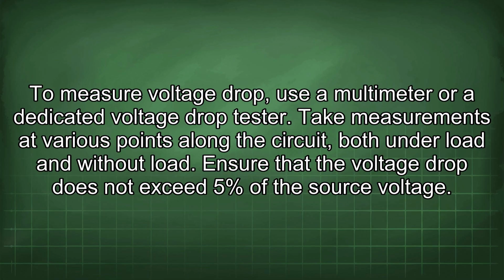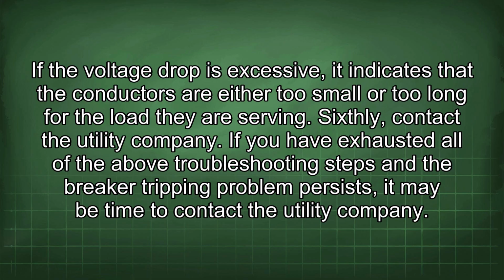Ensure that the voltage drop does not exceed 5% of the source voltage. If the voltage drop is excessive, it indicates that the conductors are either too small or too long for the load they are serving. Sixthly, contact the utility company.